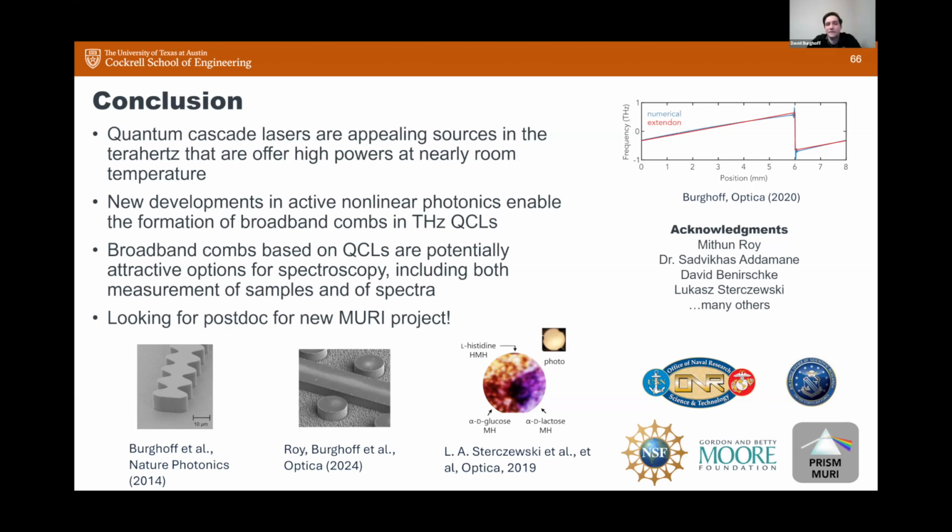Inside a wafer, it's actually very reproducible. There's always a little bit of a gradient inside a wafer, but a lot of the devices I showed, for example those involving the chirped mirrors and the gain shaping structures, relied on measurements from other devices that we fabbed before fabbing these devices. Then we took the parameters from the previous fab and applied them to make our design.